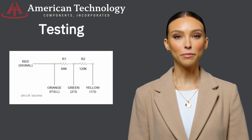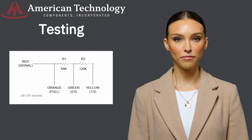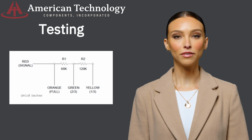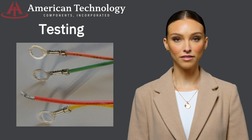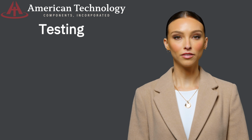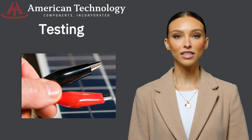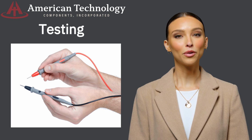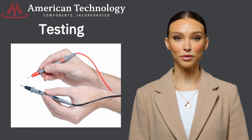Testing of the K101 is simple and quick. You will need a multimeter, preferably digital, set to measure resistance. Most meters will show that as the omega symbol or the horseshoe. When testing the K101, it is important to disconnect all the wires from the tank. It is possible for a buildup inside of the tank to act as an additional conductor and provide inaccurate readings, resulting in a failed operation of the tank level monitor. It is important to note that your body is a conductor of electricity. When measuring resistance, it is preferred to use alligator clamps so that your body resistance doesn't influence the reading of the K101. In the event that you don't have them, be sure to hold the insulated portions of the lead so as to not interfere with the readings.